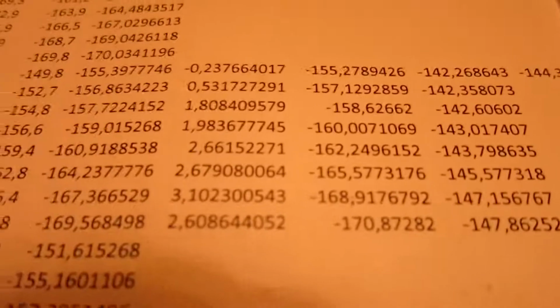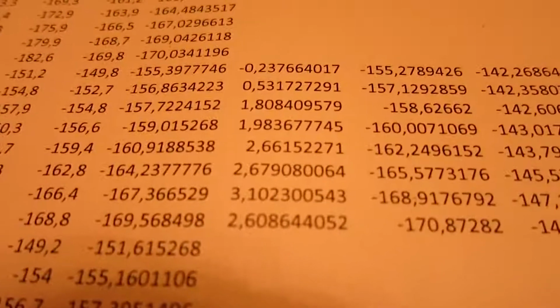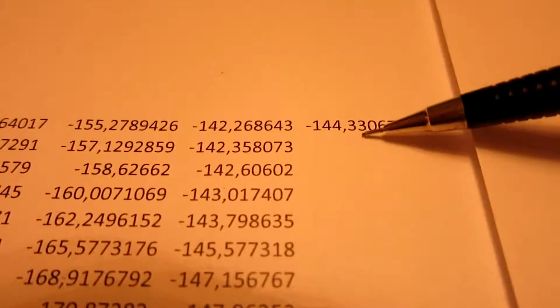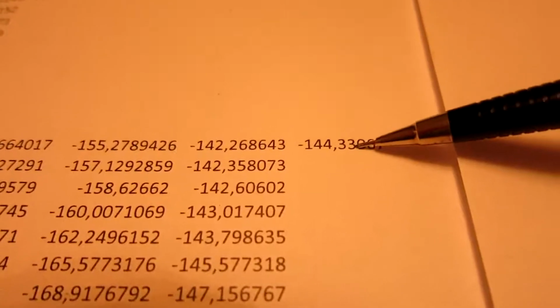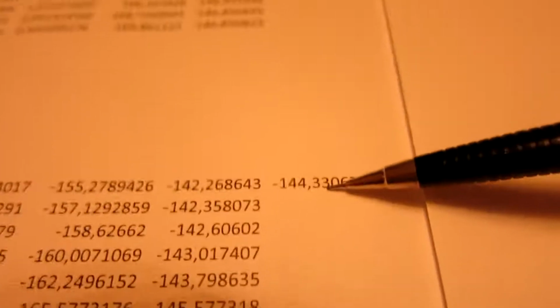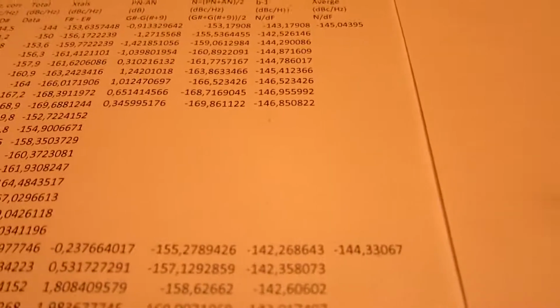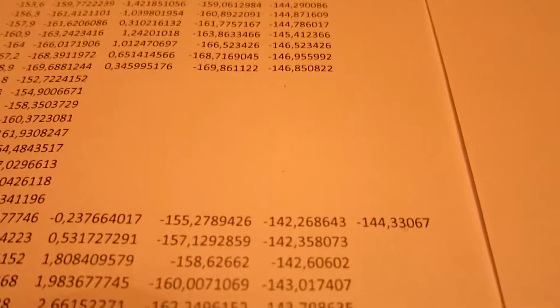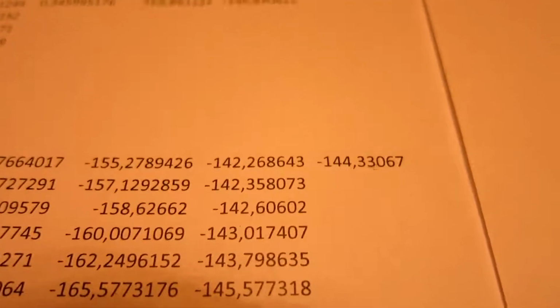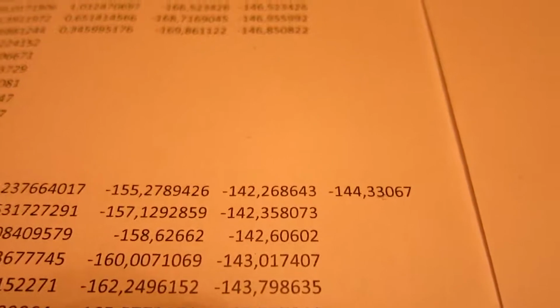And then I look at the minus 6 decibels data. They are less accurate, the differences are a little bit bigger, but when I compute the average of the B minus 1 computed the same way, I get very nearly the same result. So my conclusion is this flicker noise is independent of the power level, and it is about minus 145 dBc per Hertz at 1 Hertz.